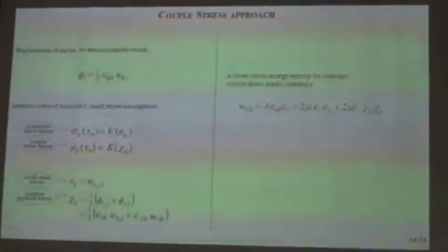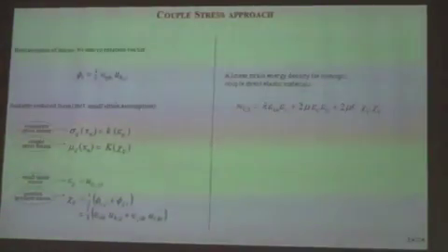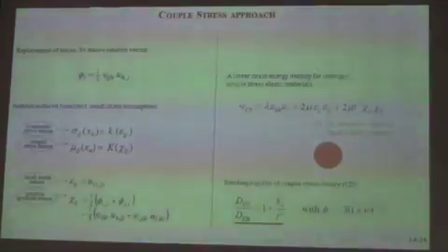And if we build in this approach the linear strain energy density for an isotropic coupled stress elastic material, we see lambda and mu as Lamé constants, and we have only one additional parameter for the rotation gradient. And this is a good thing for doing experiments.